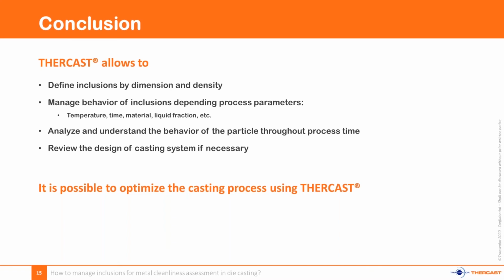So THERCAST, as you have seen, allows to define inclusion by dimension and density. It allows to manage behavior of inclusion depending on process parameters, so temperature, time, material, liquid fraction, and others. And it allows to analyze and understand the behavior of the particle through the process time, and so it can give access to how to review the design of the casting system if it's necessary. So it is really possible to optimize the casting process using THERCAST, and in particular this inclusion manager.